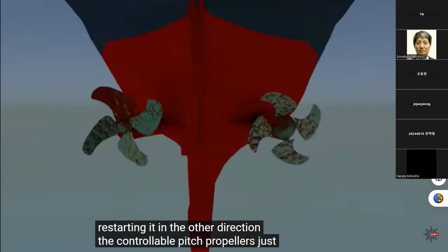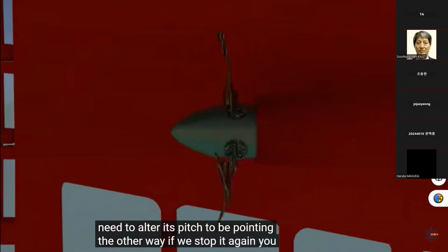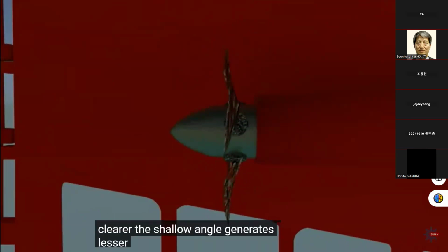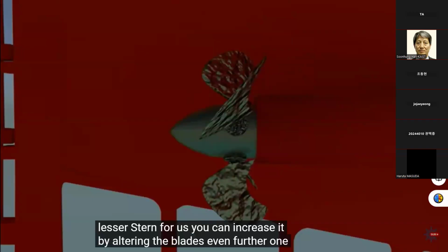The controllable pitch propeller just needs to alter its pitch to be pointing the other way. If we stop it again, you can see the alteration becomes a lot clearer. A shallow angle generates lesser stern thrust, but you can increase it by altering the blades even further.